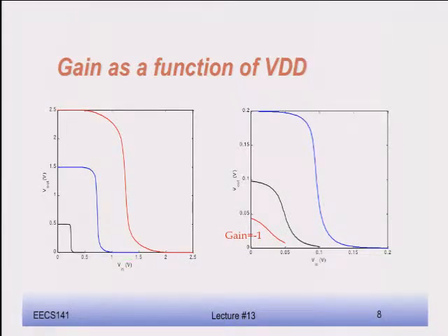The other thing it shows, what I'm showing here, is your voltage transfer characteristic of your gate as a function of the supply voltage. So this is an inverter in a given technology. I'm not changing anything. I'm just scaling the supply voltage. 2.5 volt. This is 1 volt. 1.5 volt right here. Still a very beautiful inverter, right? Perfectly fine, nice voltage transfer characteristic. I go to 0.5 volt, and I still get a very nice voltage transfer characteristic. I still get decent gain in the midpoint.